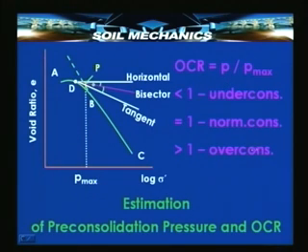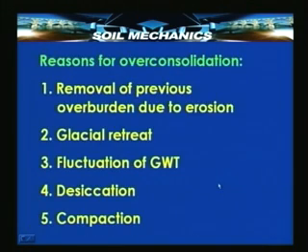If this is equal to Pmax, then the soil is normally consolidated, and if it is more than Pmax, it is over consolidated. Or to put it in other words, if the maximum pressure to which a soil has been subjected earlier is more than the present overburden pressure, then the soil is over consolidated.